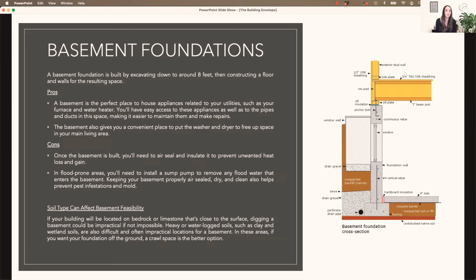So sometimes in older homes, you'll see basements that just have these teeny tiny little windows kind of up high at the top of the foundation line, just above the ground level. And so you would not be able to make that a habitable room if it didn't have an escape window. So typically when you're going to have that escape window, you're going to need this deeper well dug out. And typically the window well will come with a ladder or something for you to be able to climb out of those instances for egress.